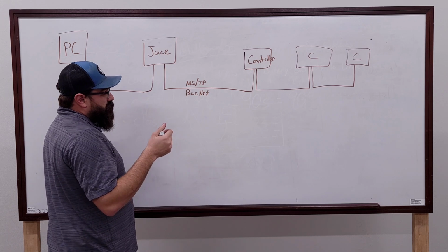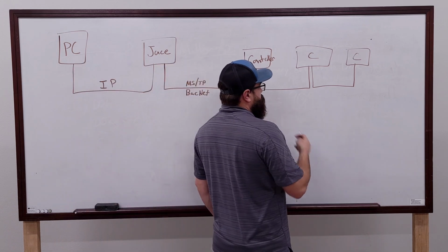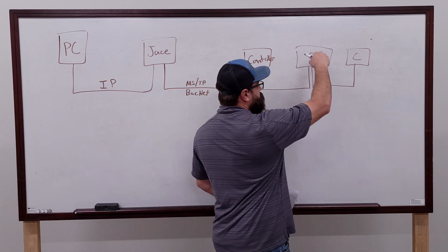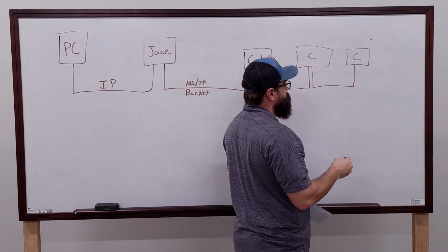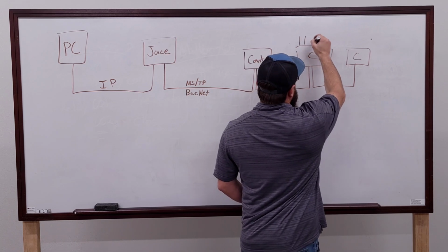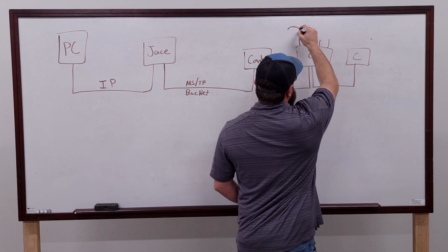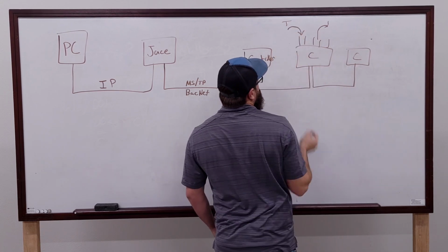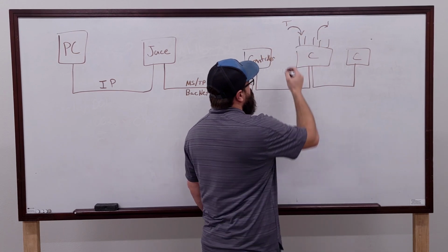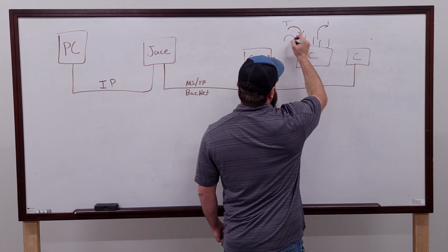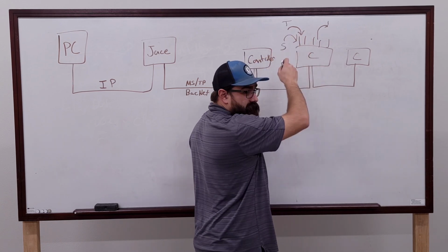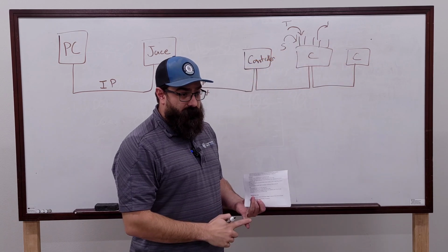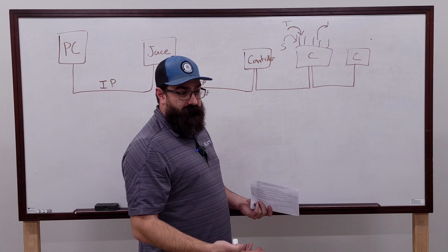Once it gets an occupancy command and a set point, this controller determines what it does with all those things. You've got ins and you've got outs. It'll take a temperature and a set point, compare the two, and then decide what to do with an output. Maybe it opens a damper, it fires a heater, whatever.